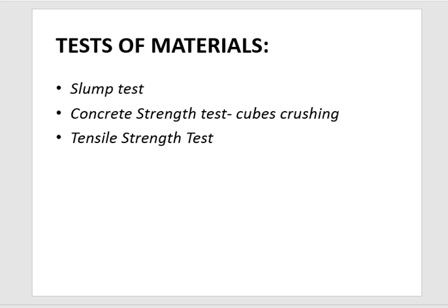There are several types in the market. So what you need to do is take samples of them to the lab where they can do the test for you, to determine the tensile strength of those materials, and you know the one you're going to procure. And the cement, yes. When we are mixing the concrete, we can take the concrete strength test so that we'll be able to know the quality of the cement.